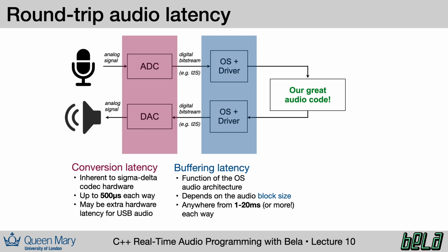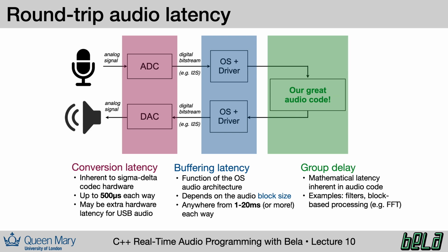It typically happens in the operating system and the audio driver before our audio processing callback is ever even called. The amount of latency here depends directly on the audio block size and might range anywhere from 1 to several dozen milliseconds. Finally, it's important to remember that our audio code itself can generate latency.